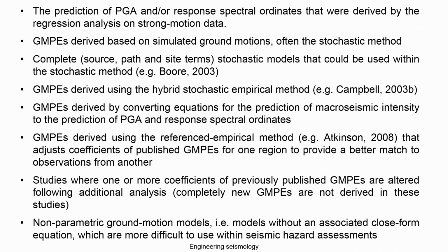What I discussed, the different seismotectonic things. So one has to focus on the development of those kinds of models which are required for the country. So this model, as I told you, the prediction of PGA and the response spectral ordinates were derived by regression analysis of strong motion data. So generally they take recorded data or simulated data and pick up peak values with respective magnitude and distance, and for similar conditions. Similar conditions means the data from bedrock has to be used only for the bedrock.